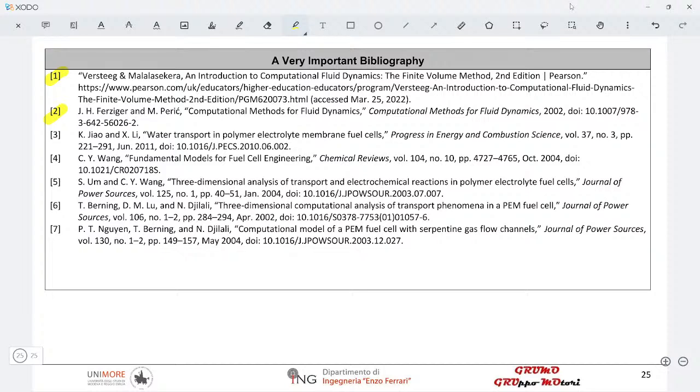So how can you replicate this? Typically the most common choice, which makes sense, is to use a 0 or 1-dimensional model of your stack. You mentioned the pressure losses and the reactant feeding of each cell. You might use a lower order model of your entire stack to derive the pressure losses and use this as a generator of boundary conditions for your individual cells.